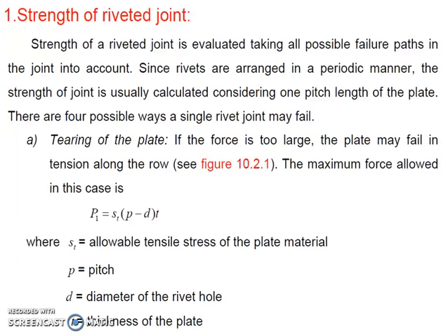Now it is to be noted here that while we are using the allowable tensile stress of the plate material, the materials that we are going to connect should be of similar thickness when two plates are connected to each other, because it makes it easier to do the load distribution and much of the load is then easily transferred.